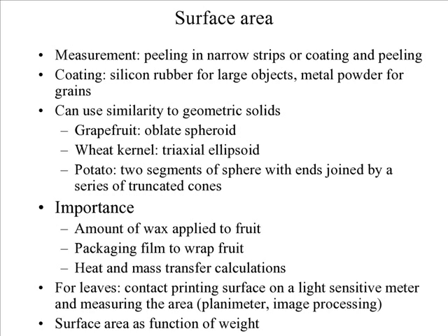In terms of importance, the surface area is important when you're calculating the amount of wax applied to fruit, when you're considering the packaging film needed to wrap fruit, and also for heat and mass transfer calculations, which are proportionate to the surface area. For leaves, you use contact printing on a light-sensitive surface and measure the area with a planimeter or do image processing. And the surface area is also a function of the weight, and that can be a way that you find it.